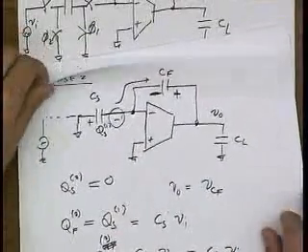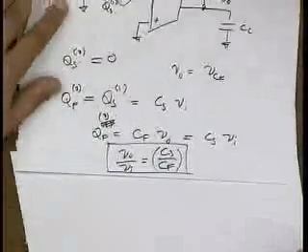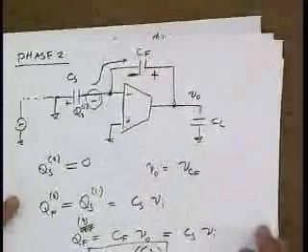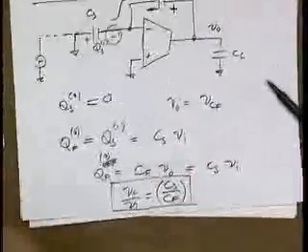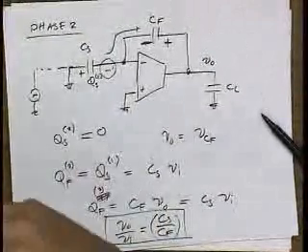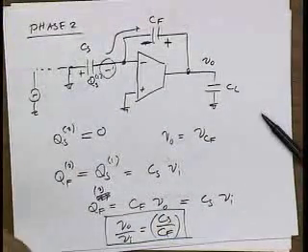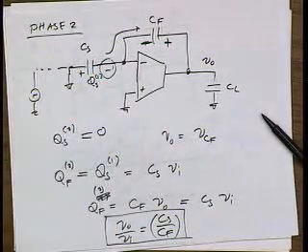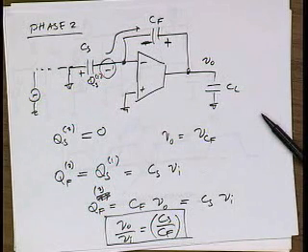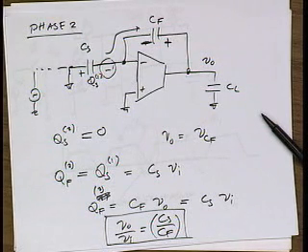Good. So that's how a switch capacitor circuit works. Why is it that these circuits weren't popular with bipolars? It really took CMOS to make switch capacitor circuits popular. Simple question: why not do this with bipolar? Yeah, CMOS has good switches. We don't have good switches in bipolar, right? Bipolar switches have offset voltages. So you can turn it on and off very well, but you always end up with an offset voltage.